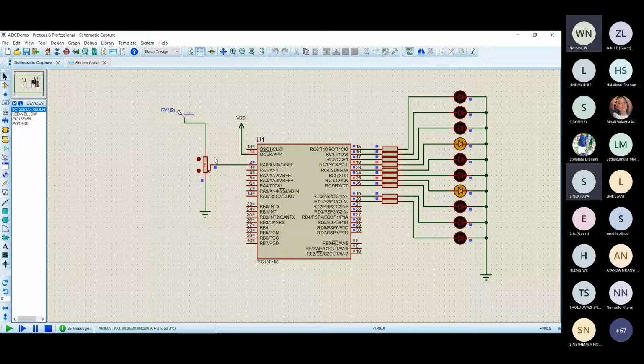We can take a potentiometer as a form of transducer, because we are working on the resistance here, but we are controlling the voltage that we are supplying on this pin. With the digital input, we send 0 and 5 volts. But with this setup, the voltage we are sending is the portion between this ground and the pointer.